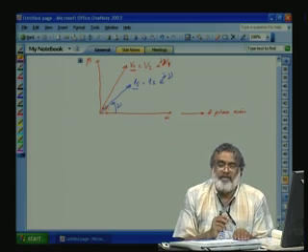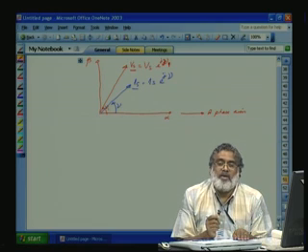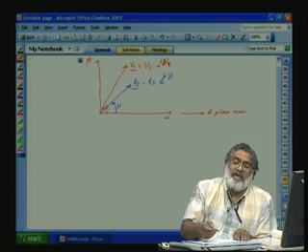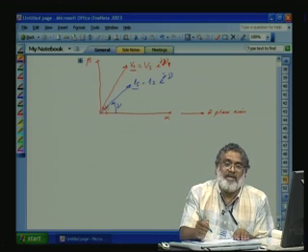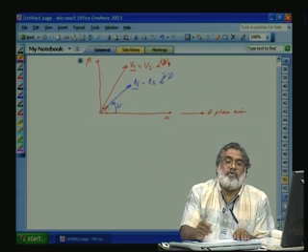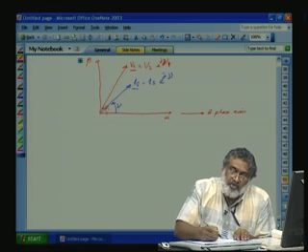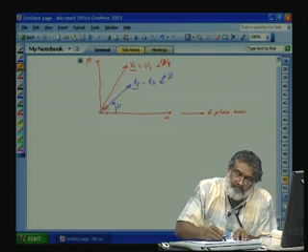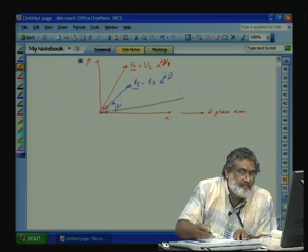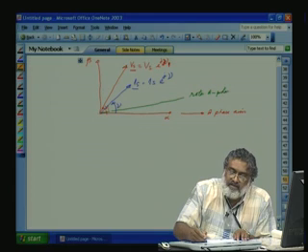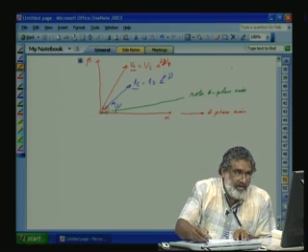Now, the rotor is rotating. So, if you see, the rotor ABC axis will have a varying angle with respect to the stator ABC axis, and the rate of change of angle is proportional to the rotor speed. So, let us say the rotor axis is somewhere here, the rotor A phase axis. Okay, I will write it bold.